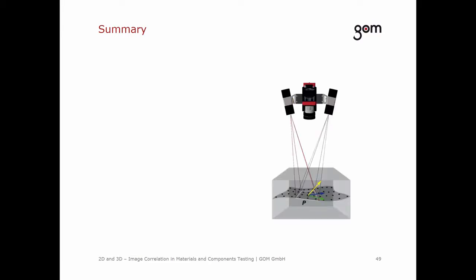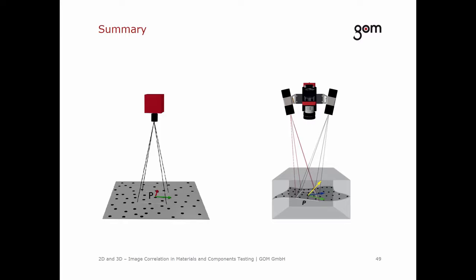To sum up, a stereo camera system is the best way to optically capture coordinates completely. It provides extensive measuring data. Besides, it is a more robust system. The system can be set up very flexibly. 2D measurements, captured with only one camera, are good enough when you can tolerate the limitations. 2D measurements are often used for very small specimens or if you have a high-speed test.